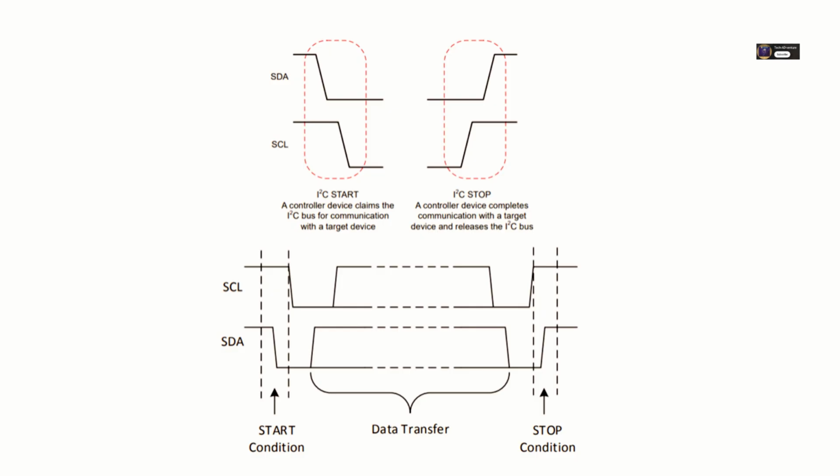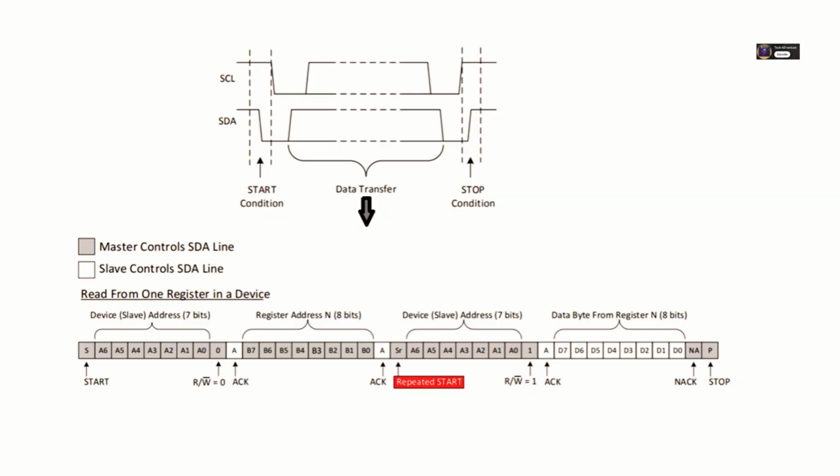So putting it all together, what's the structure of a typical I²C data transfer, like the whole sequence? Okay, a standard frame looks like this. Start condition, then the slave address plus R/W bit. The addressed slave must respond with an ACK. Then, depending on R/W, either the master sends data bytes, each followed by an ACK from the slave, or the slave sends data bytes, each followed by an ACK from the master until the last byte, which gets a NACK. Finally, the master sends the stop condition.